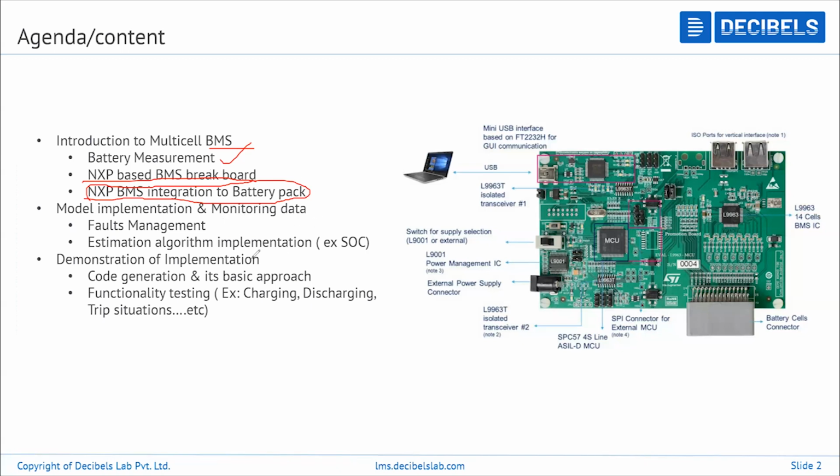Once you develop a MATLAB Simulink based model, there you have built up your algorithms and the logics related to cutoffs or monitoring, and then whatever the model is, you need to dump that particular logic to the controller. So how it can be done on the NXP board, that we can look into.